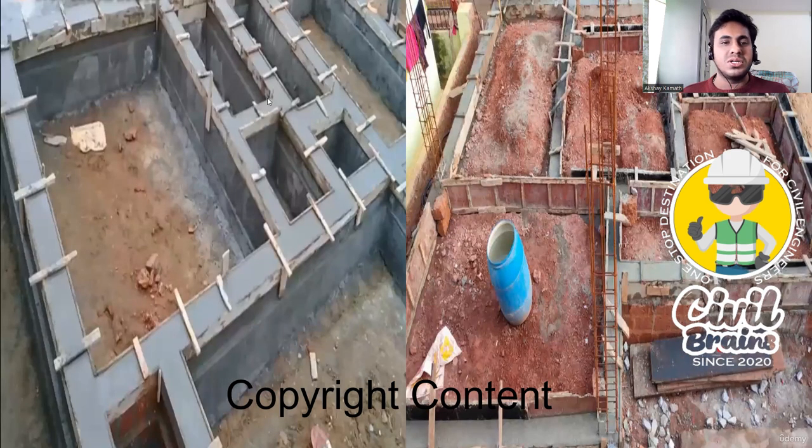Yeah, so just concentrate here. This is somewhat, yeah, this case. You see here, this particular case it is. So if I want to find the shuttering of this beam, it's very simple. This outer length to this outer length I'll take, multiply this by the depth, and I'll get the shuttering of this side.